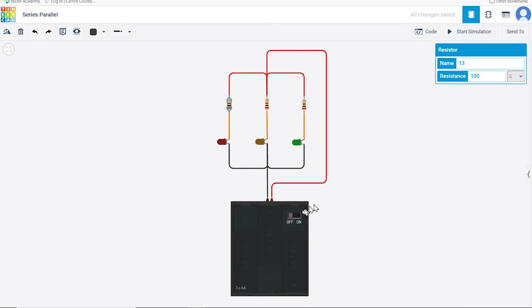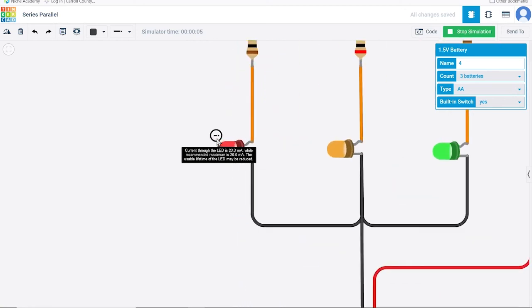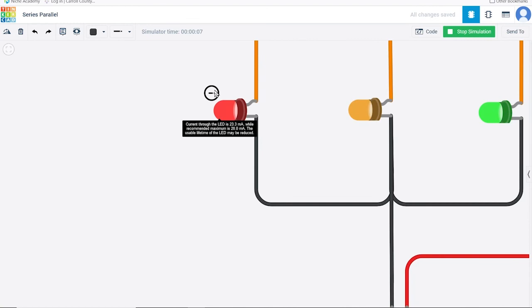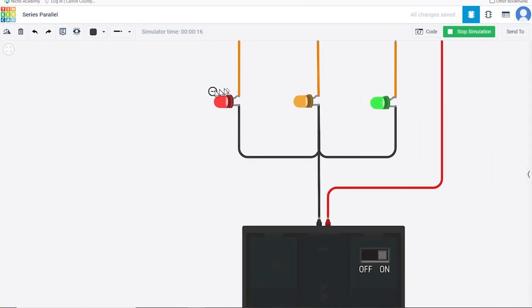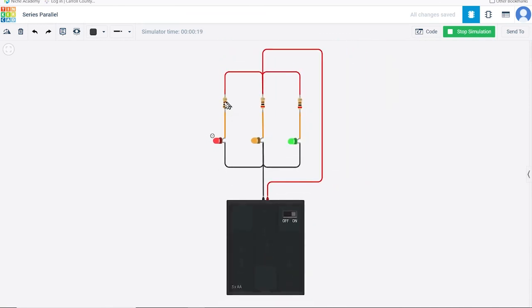In addition to a specified operating voltage, LEDs are sensitive devices, and if too much current flows through one, it can be destroyed. To mitigate this risk, we'll add a single resistor in series with the LED. This has the effect of limiting the current through each LED and is said to be a current limiting resistor. We'll see a lot of this type of circuit protection in Arduino circuits as we explore further on. By choosing the appropriate value for each current limiting resistor, we can operate LEDs at a maximum brightness level without the risk of burning them out.